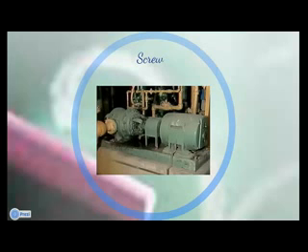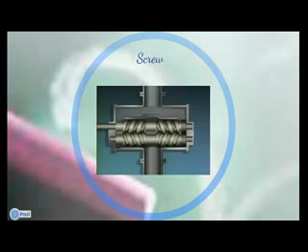Progressive cavity pumps are especially useful for moving extremely thick fluids, such as sludges and gels, since they can move these fluids without clogging. Another type of screw pump is the two-screw pump that's represented here. One of the screws is attached to a shaft that is coupled to the pump's driver. This screw is the driver screw. It's sometimes called the power screw.